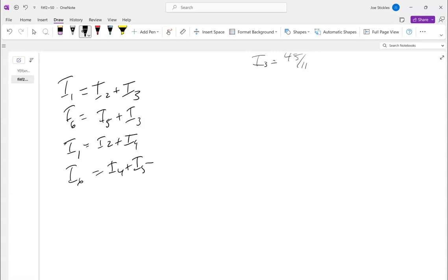Going around this way. Yeah? That's the only resistor we have. Do you agree? How much voltage gain do we have when we go around? Yeah, they've got this one and that one, right? So there's 20. So our 10I1 will be 20, which makes I1 really easy to solve for, but we're just setting up the equations, yeah?